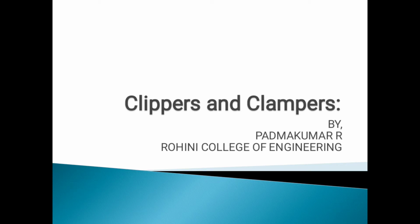Clippers and clampers: the positive clipper and the negative clipper. A positive clipper is a circuit that removes the positive parts of the input signal. It can be formed using an op amp and a rectifying diode. The clipping level is determined by the reference voltage Vref, which should be less than the input range and the output amplitude.